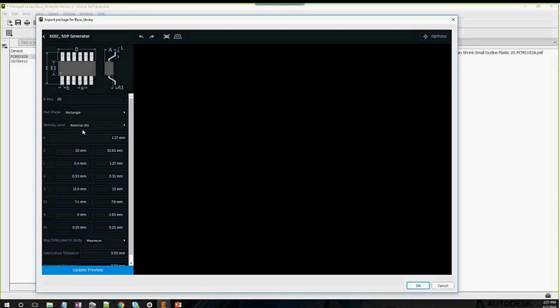So first and foremost, this E, it gives me that it can be either 6.2 at a minimum and 6.6 at a maximum. So I'll put that there. I'll put this over here, 6.6. Okay, for the L, minimum is 0.5, maximum 0.75. I'm grabbing all of this straight off the data sheet.